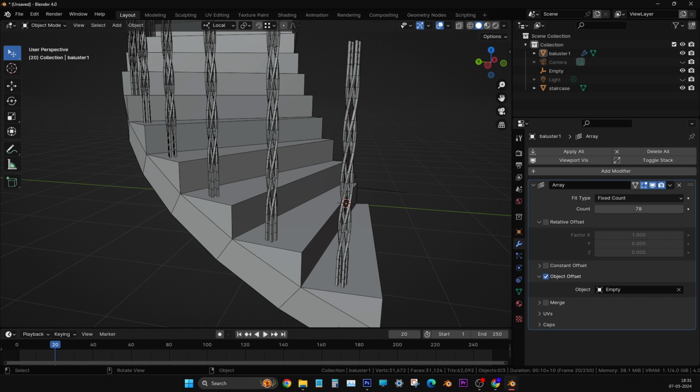Now, you press Control Space. There is this back to previous option. Just press Control Space again. Do you see that back to previous? That is Control Space actually. If you don't remember, you can just press that and get back the outliner, properties editor, everything in view. Sometimes you want to maximize the view, for that Control Space. That's all.